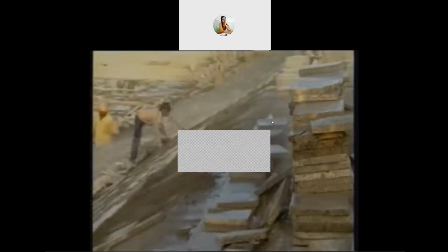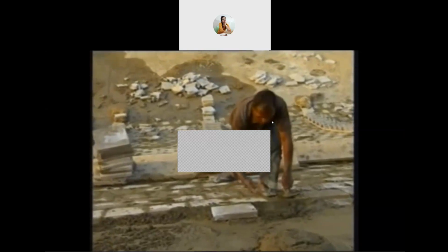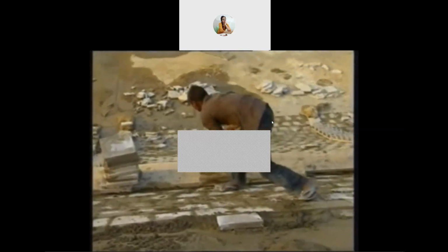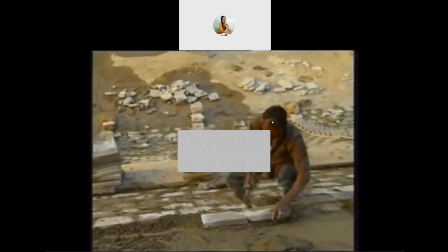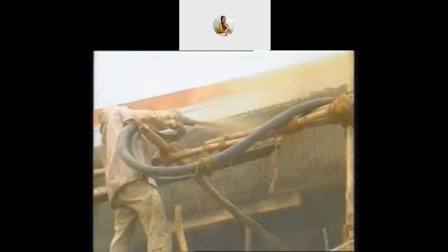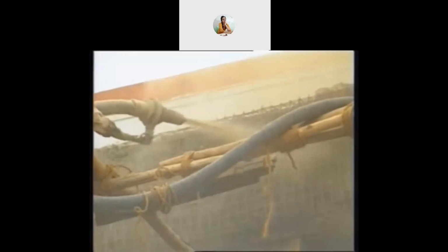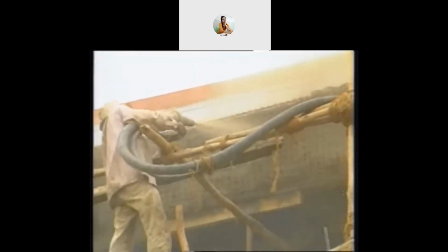Precast concrete tiles are more compact and impervious. These tiles are laid in 1:3 cement mortar in single or double layers directly on the compact subgrade. In shotcrete lining, cement mortar is applied by pneumatic pressure. It can be placed over rough subgrade. Sandstone lining is used in field channels depending upon its availability and cost effectiveness.